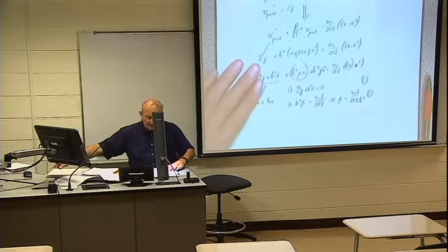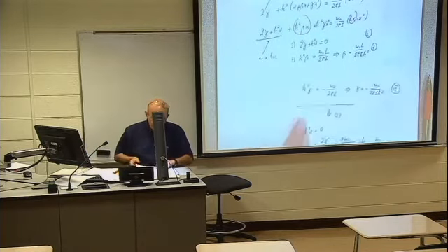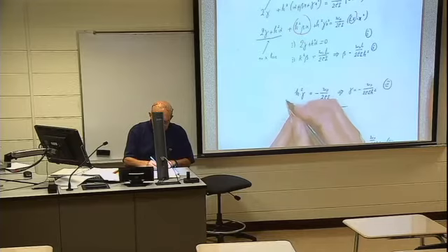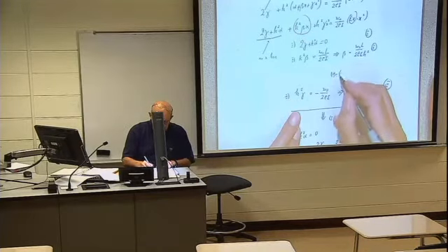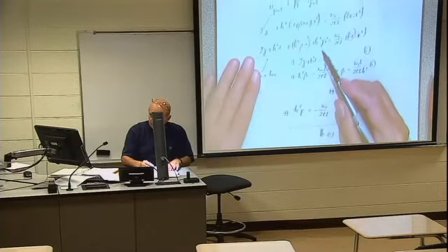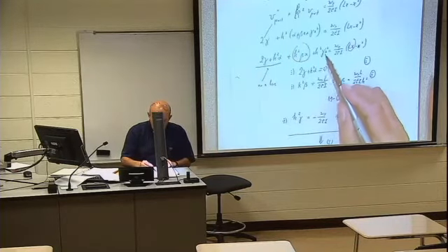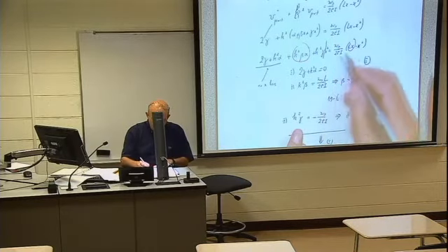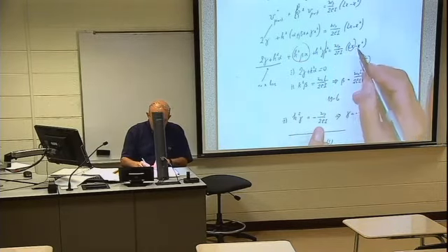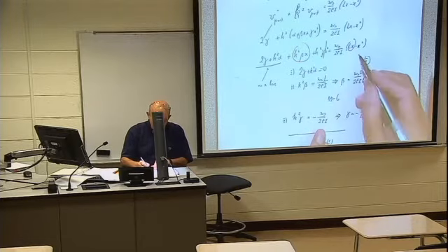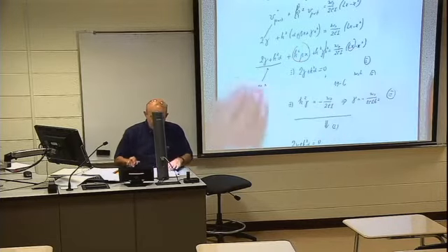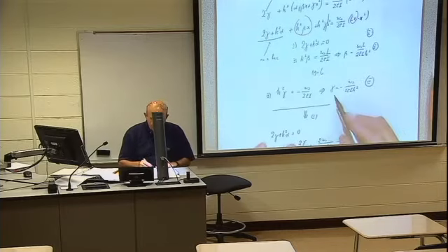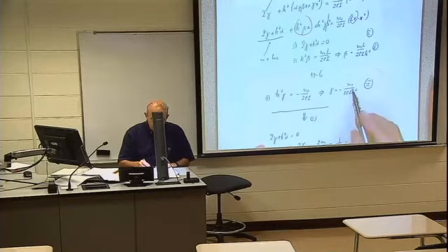So then the third equation. K squared gamma, that is x squared. K squared gamma equals minus W0 over 2EI. From here we get gamma. Gamma equals minus W0 over 2EI k squared.